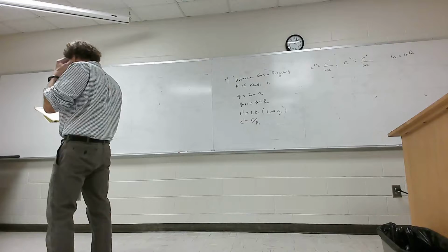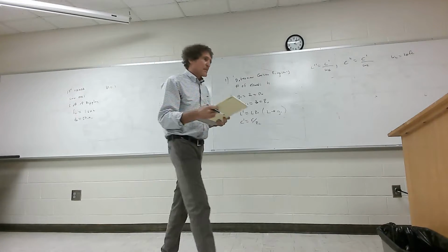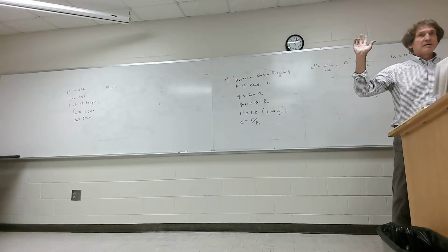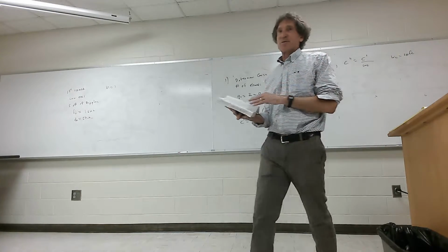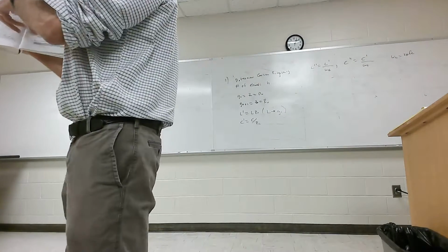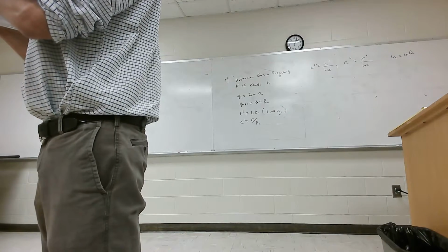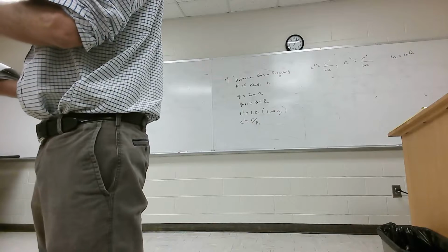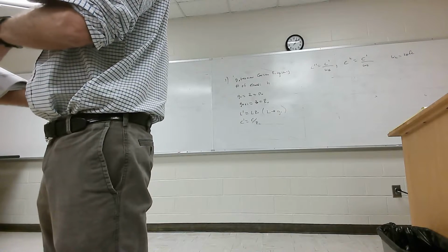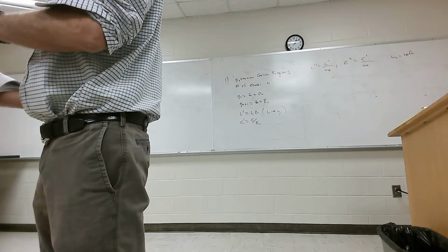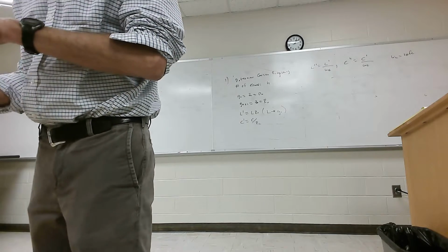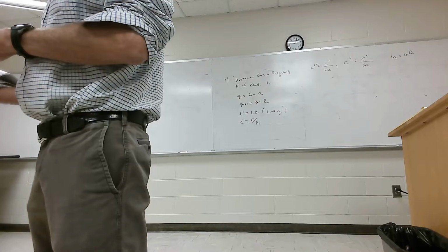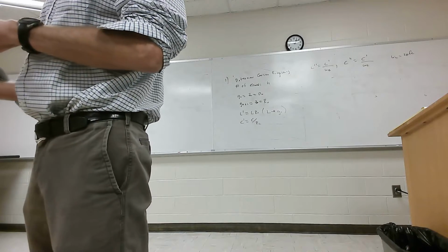So for this one, if you look at the table now, in his book, how many have your books here? I'm just going to show you. If you look at this table, there are 3 sets of values for these G values. The top one is for 0.1 dB of ripple, which is very small ripple. The second one is 1 dB of ripple, and the third is 3 dB of ripple. That would be on the insertion loss graph.